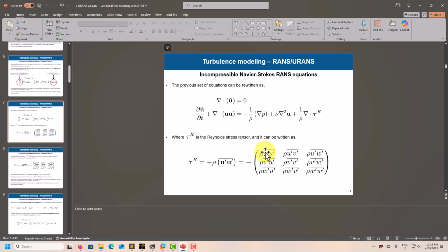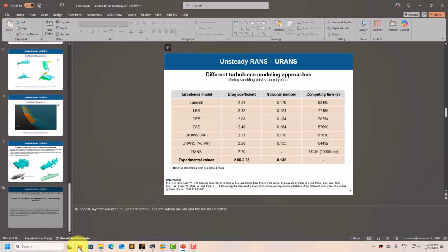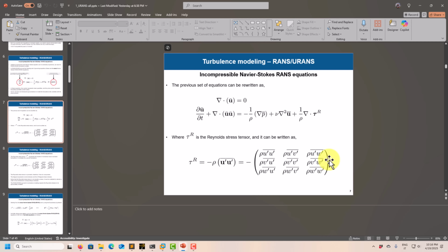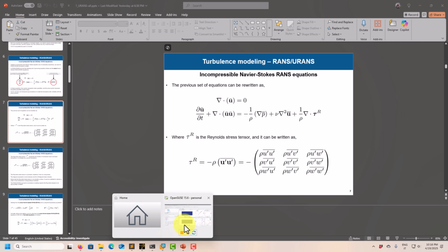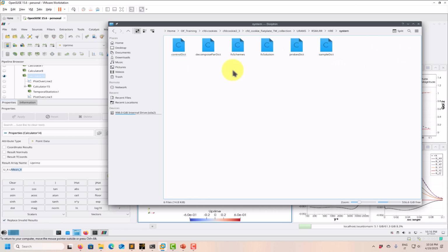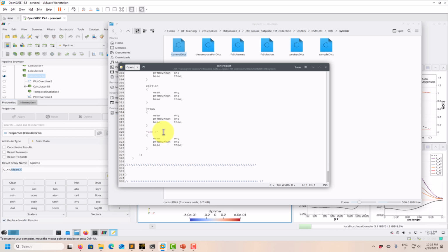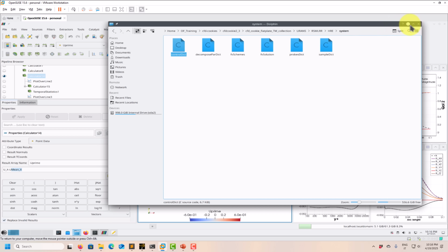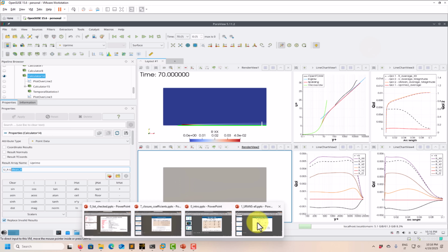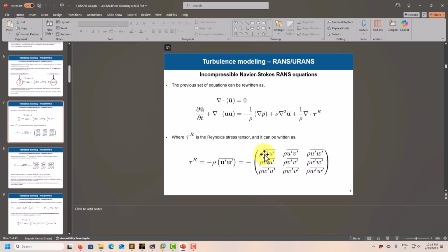So we'll compute this quantity in OpenFOAM: U prime, you multiply, and then when you have this product, you average that product. This stuff here is the U prime that you see in the OpenFOAM dictionary, and let me open that dictionary. It's in here. When you have the statistics, that quantity there is prime to mean. Prime to mean is basically this quantity. So it will be for whatever quantity, pressure, velocity, and so on. So that's why you use velocity as the Reynolds stress.